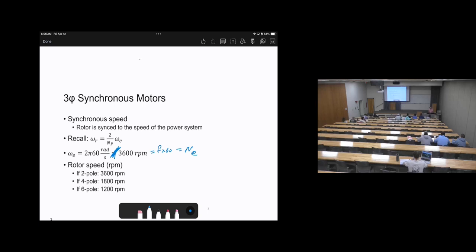So again, like 75% of the motors are induction, not synchronous, which is the motor that we will discuss next lecture. Why? What's the point of this? Recall when I discussed the generator, the synchronous was suitable for constant speed applications. So when we need to use the electrical motor, how about if the speed is not constant? How can I control the speed?